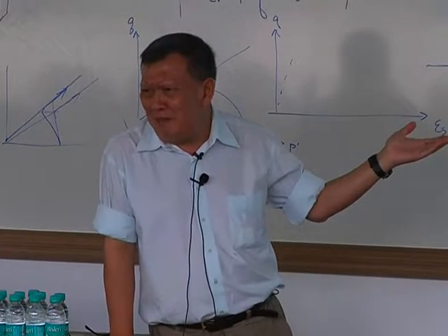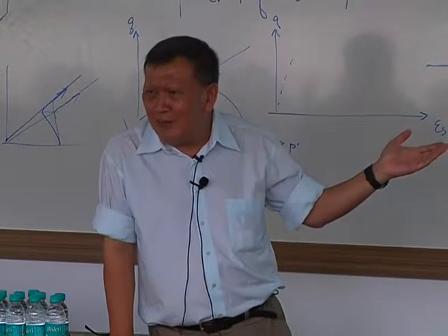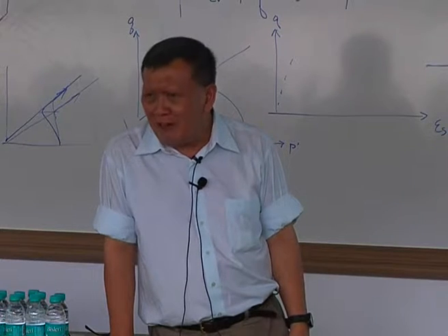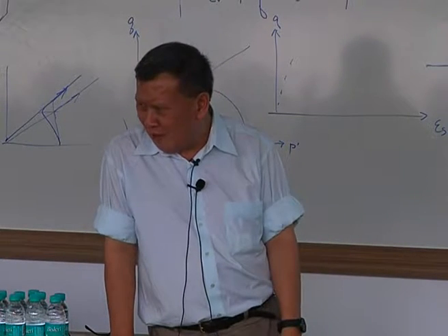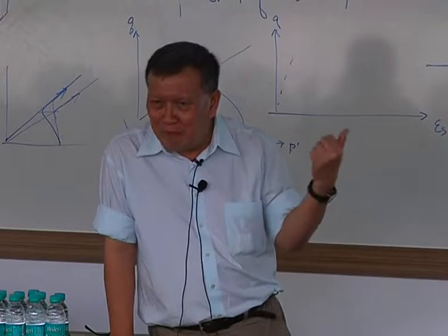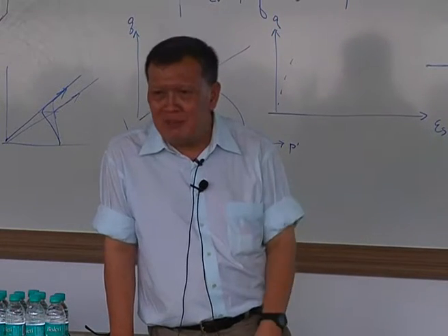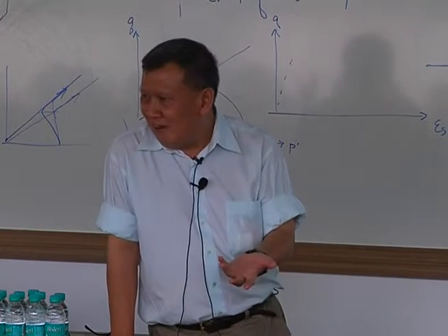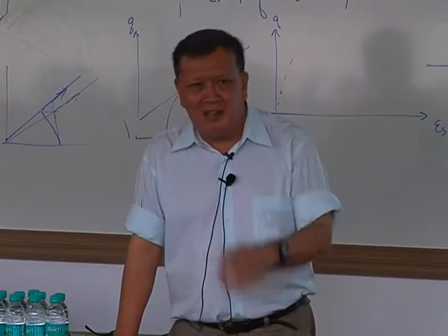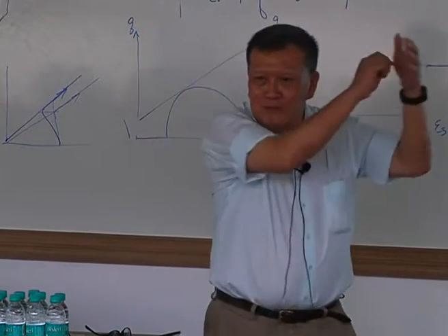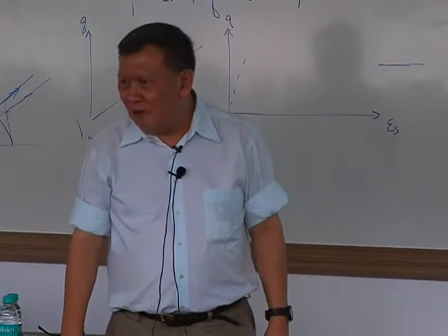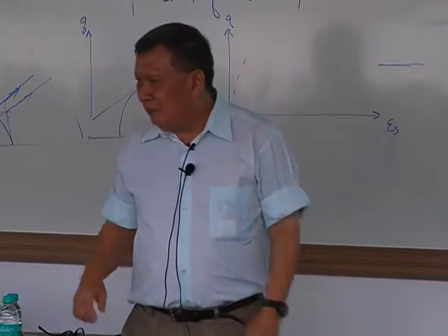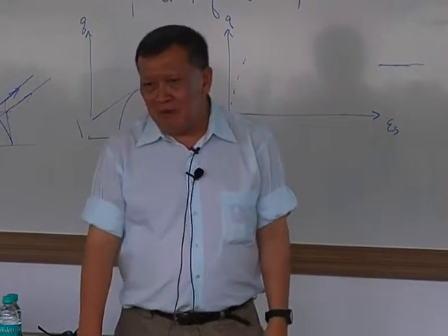You should do the parametric study and tell the client, if you're looking at the bending moment of pile, use 5-degree angle of dilation, this is the largest bending moment you've got to get. If you're looking at the movement of the wall, use 0 angle of dilation, that is the largest movement you get. Correct or not? That is what you ought to do. There's no such thing as a biblical truth somewhere that lists out all the do's and don'ts. It doesn't happen. So at the end of the day, you still got to do your parametric study.